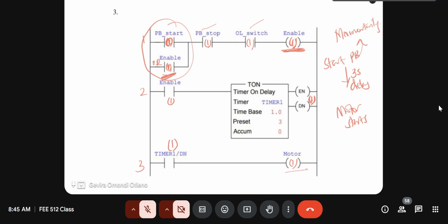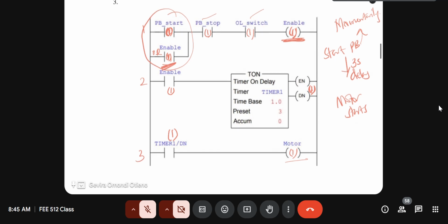Okay, unless there's a unique position where you want to start the motor, but you want to move far away before the motor starts because of the conditions. Maybe the motor is so loud, or the conditions there can be dusty, and maybe you don't want to put yourself at risk. So you press the button, you have a delay of some time to walk away to safety before the motor begins. So maybe that's the condition where the motor is, but usually, again, you can wire the start button to be closer to you and the motor very far away from you.